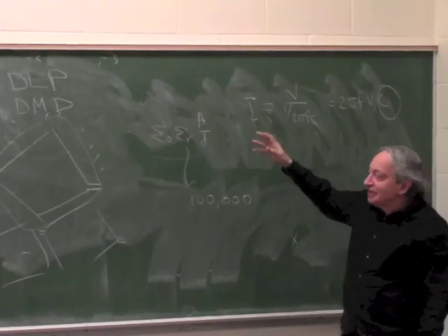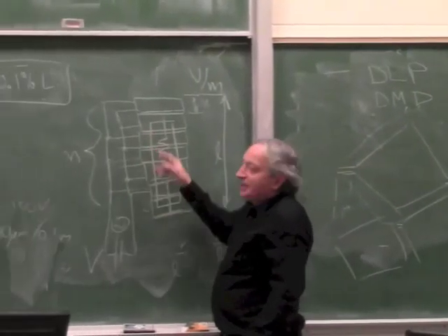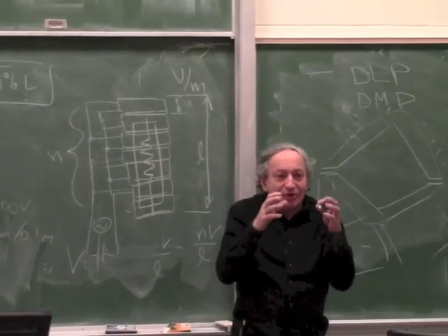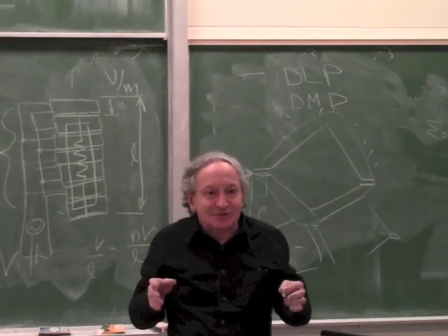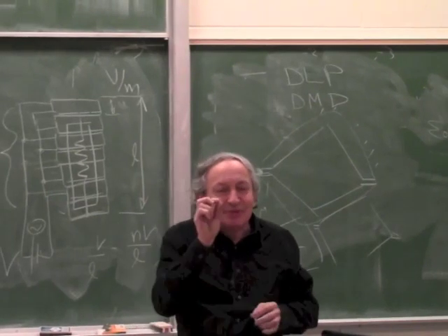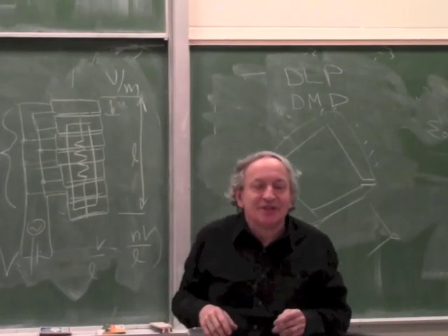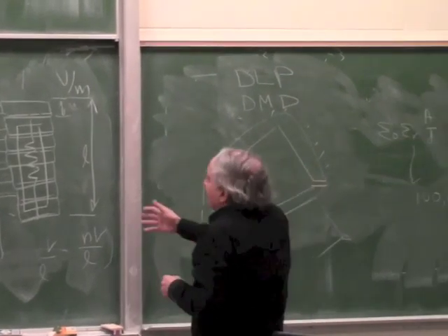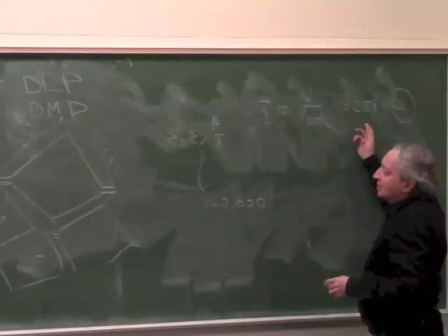So on first sight it looks like it's a perfect actuator. You linearize it with a strain gauge, and it's a monoblock, it doesn't have any hinges or moving parts. In practice it's not very useful. It's useful when you make very miniature things, but as a bigger actuator it's pretty useless, because you find right away you cannot drive it fast, because the capacitance ends up a huge number.